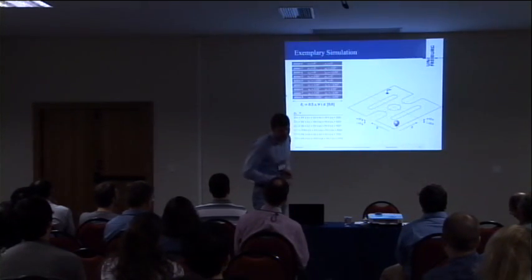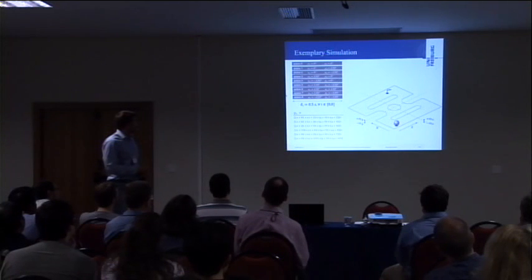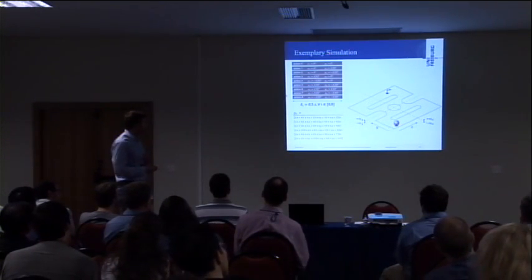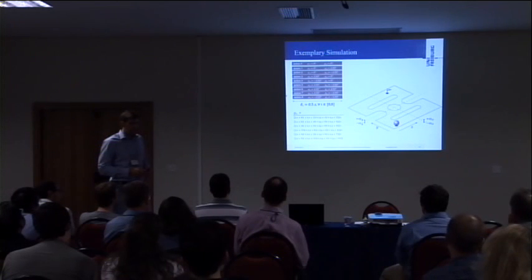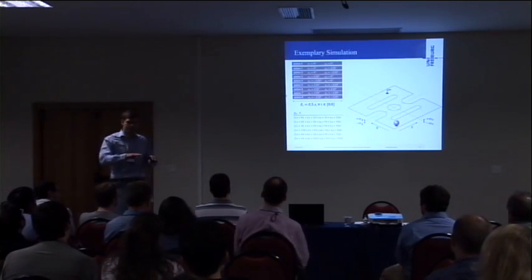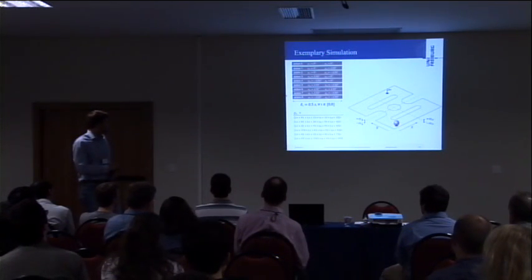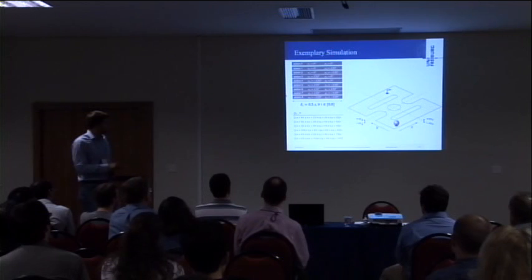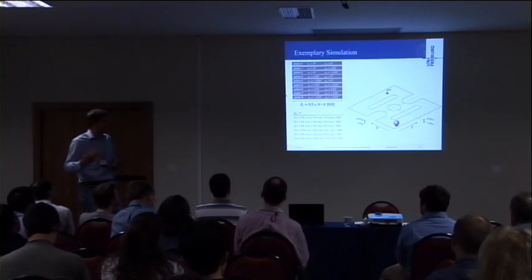We also did some feasibility analysis. We have here the task that we have to bring a small ball, a dynamic system with a position and a velocity, on this tilt table to a state satisfying some goal conditions, so a small flag here. Therefore we can incline the plate around 2 axes, leading to 9 different plate inclinations, each having an operation duration delta t of half a second. The holes and the edges of the plate are simply modeled by preconditions, so we check in each state if we have fallen into a hole, and if not, we can continue with the planning process.